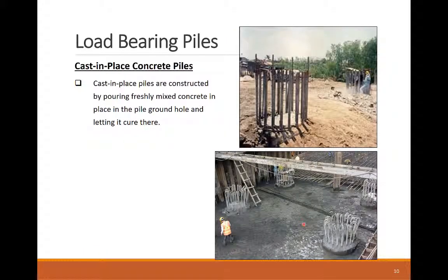Cast-in-place concrete piles are one of the most versatile piling approaches, but it requires more concrete resources and a hefty budget. Cast-in-place concrete entails digging the pile holes and casting the concrete inside the holes after dropping the required reinforcement. The top photo shows the constructed piles extending to the ground level, while the bottom photo shows the piles constructed up to the basement level inside a deep foundation deck.